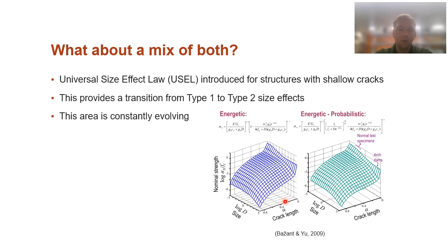And then when we do introduce a crack length, let's say on this side of the spectrum, that's where we see this drop off with increasing size here that kind of just heads straight towards zero. So that's important, and we'll think about that. But there can exist a region in between your crack lengths where they play a role in the strength too. So it does exist.